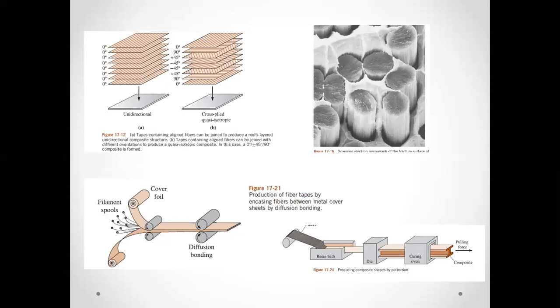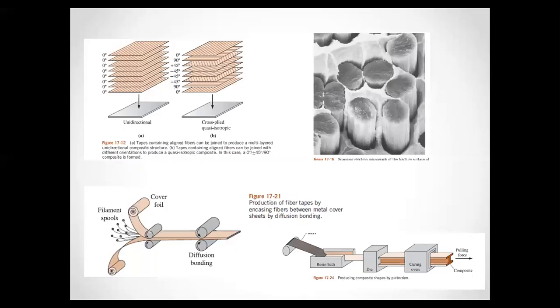So if you rotate your layers, you will have different properties. You would have seen in the last unit why diamond is so strong. This is because of two planes which cross. Diamond is made of two FCC cells placed one over the other, so if you cut a diamond, you go across two different planes. That makes it very strong. If you compare these two materials, this one will be much stronger because it goes on different planes in different directions, so it will be much stronger than this material.